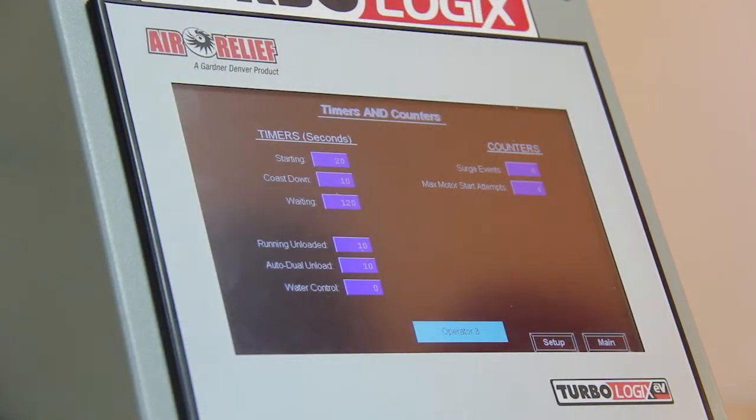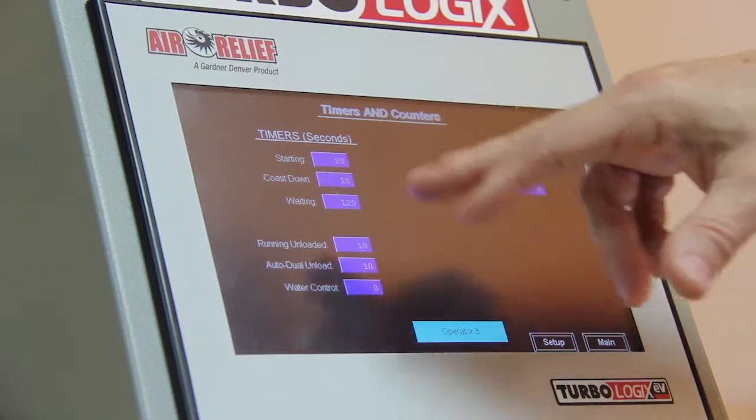Now, we also tie our alarm and trip multipliers to that, and there are also some bypasses on the digital inputs that are tied to that value as well. So basically, we fire off a 2x multiplier, for example, with your vibration. In the setup for your vibration input, you would say, I want a 2 times multiplier. In that situation, during the start of the machine, you will have 20 seconds by which the alarm and trip limits are doubled on that compressor, and that's tied to that.